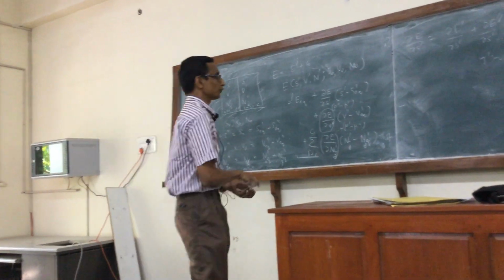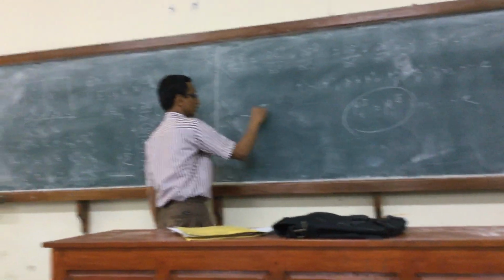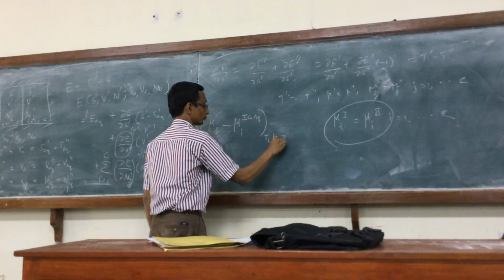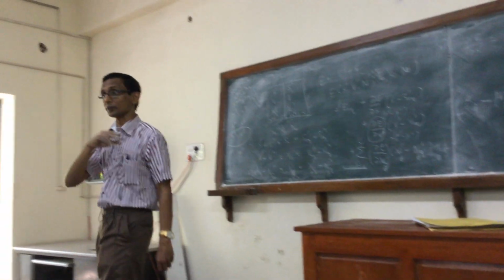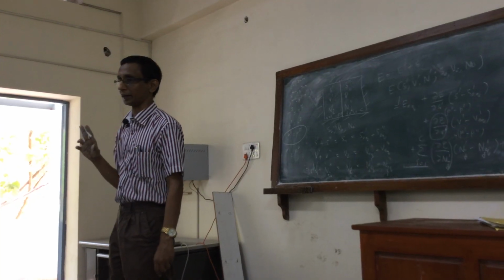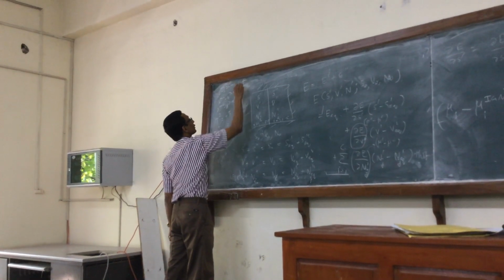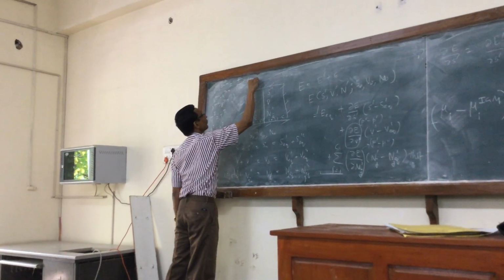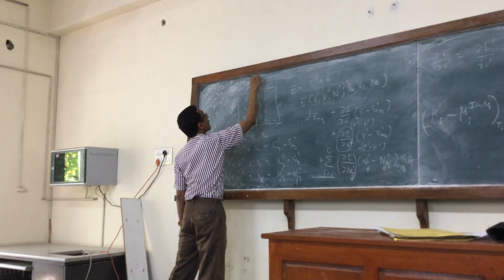So for that, what we need really is mu I, the departure, which we can relate to the equation of state. This is what we want. So far we have looked at departure functions for the specific property. Now this is like a partial molar property. We avoid it. Actually, for instance, this can also be written as a sum over I equal to 1 to C, of Z I times E I partial molar minus E I partial molar ideal gas mixture.